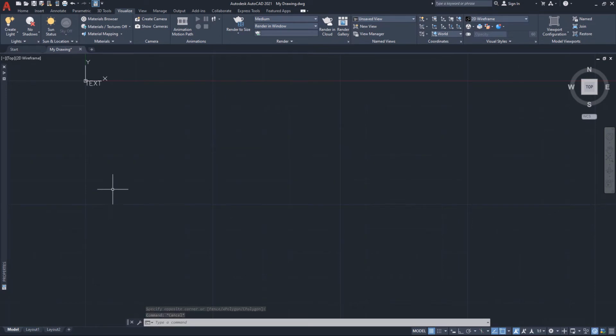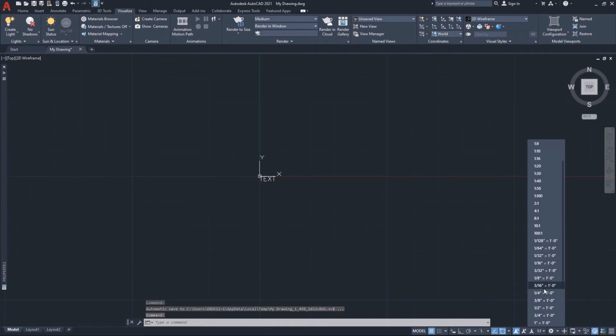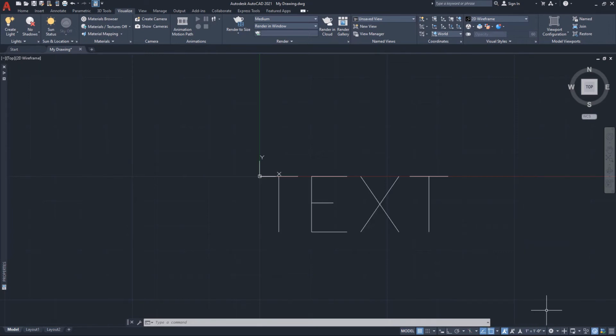We again only see the actual 1:1 annotative scale iteration in correlation to the annotative scale assigned in the Drawing Aids toolbar at the lower right of the display. Left-click one time on the Annotation Scale pull-down and change the current scale to 1 inch equals 1 foot, 0 inches, and note the graphic change in the font height.